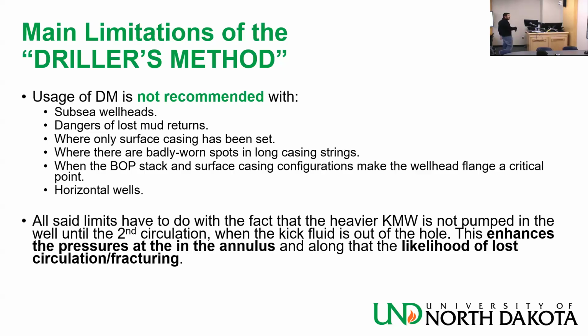It's not recommended, but like I said, the experience of the crew is what matters. If they are very familiar with the driller's method and this is what they want to use, I will use that. All said limits have to do with the fact that the heavier kill mud weight is not pumped in the well until the second circulation when the kick is out of the hole. This increases the pressures in the annulus, and along with that, the likelihood of lost circulation, fracturing. Fracturing is basically underground blowout.